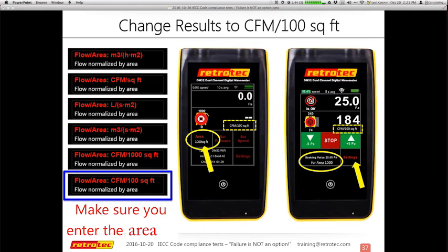And you can see on the screen in the middle, it shows what a square footage, an area. The area is 100,000 square feet. And even while I'm doing my test at the bottom, it tells me how big the area is for my results. One of the common mistakes is you may go from one house to another, and you got to make sure you enter the new, it should say area, there on the bottom. Because area is for the duct tester, volume is for blower door. I'm sure I copied the text from one to the other.